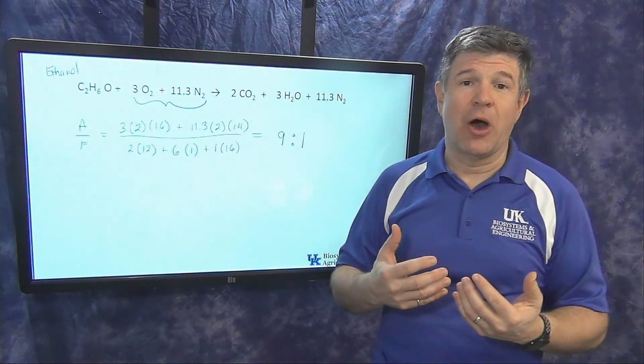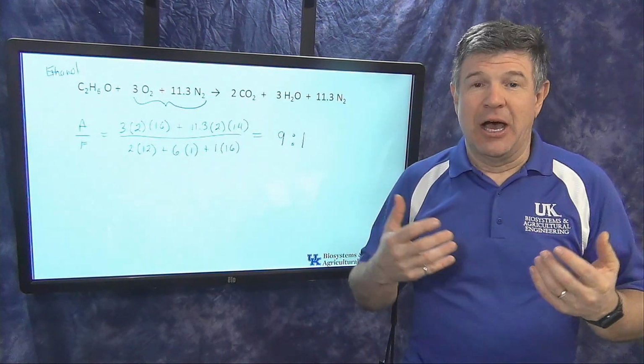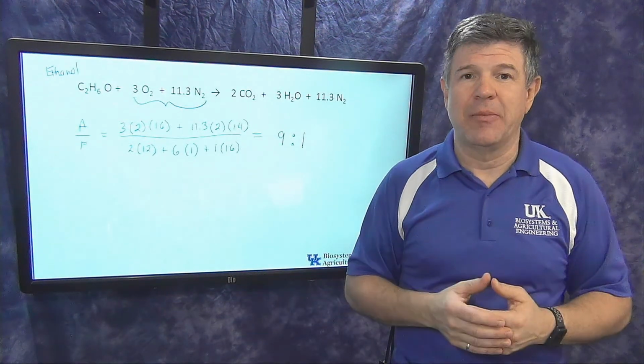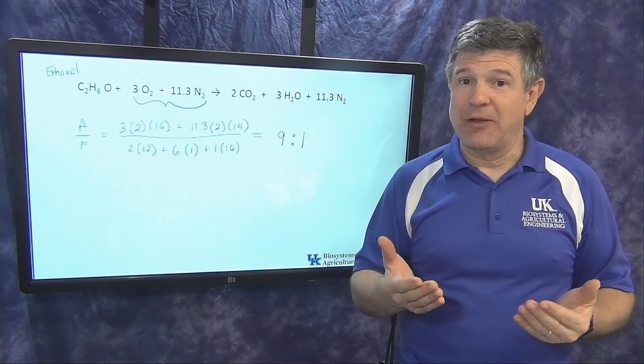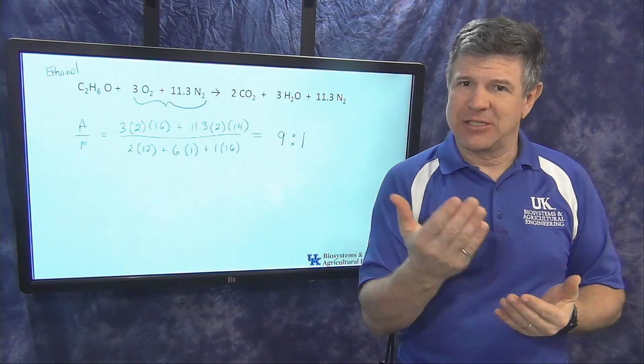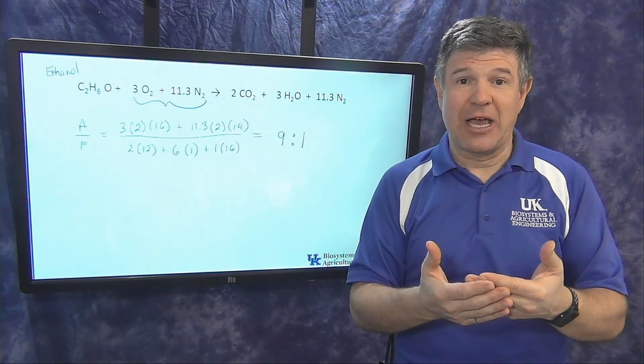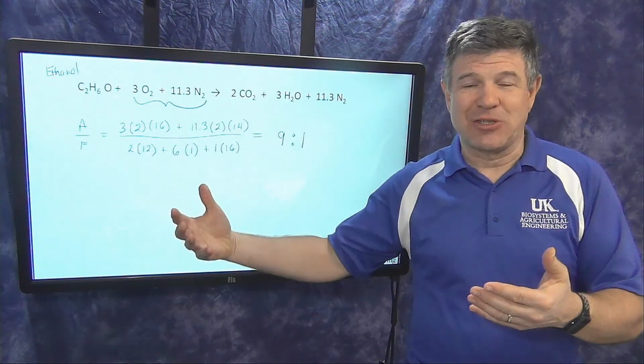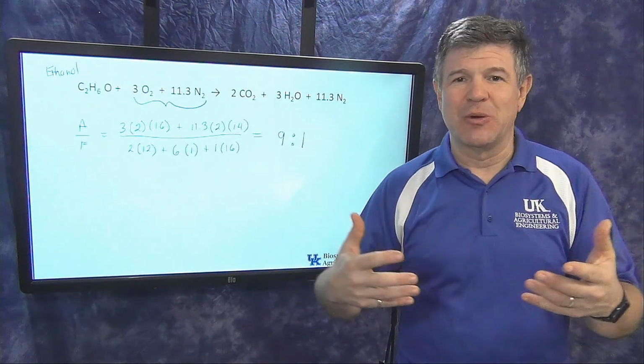If you've got an automobile that is a flex fuel automobile that can run ethanol or gasoline or any combination thereof, what they're doing in that vehicle is they've got sensors. They've got a sensor in the fuel that figures out how much oxygen is in that fuel, and they're looking at how much oxygen is going out the exhaust, and they're doing balances on that.